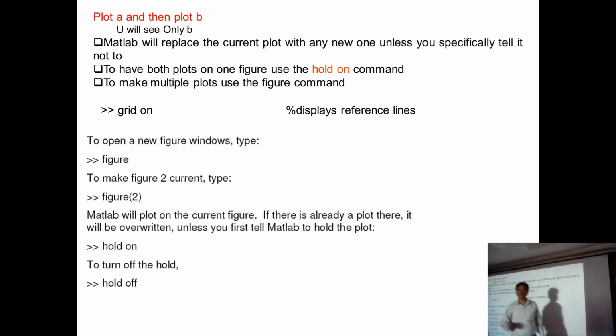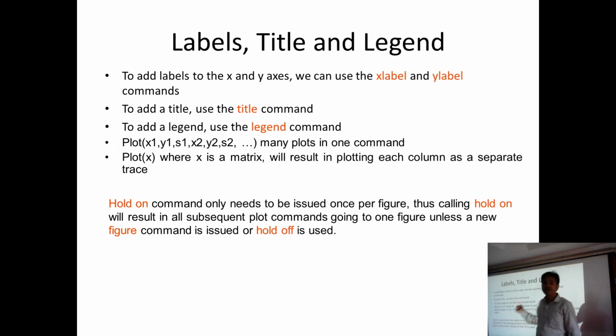We will see. Here I have written, and the advantage of MATLAB is you can go with multiple plots on the same graph. Plot of x1 comma y1 comma s1, x2 comma y2 comma s2. That means on the same graph, I can put so many curves.